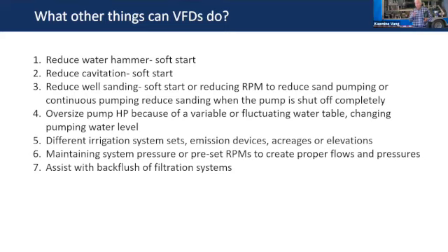Also, a lot of ranches where they've had major issues with this, they'll keep that pump running at a lower speed all the time, and it never shuts off completely. And they're pulling very little horsepower when they do that, and they're able to keep sand from being an issue.